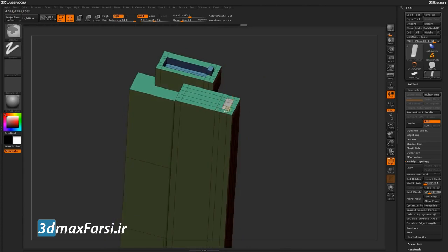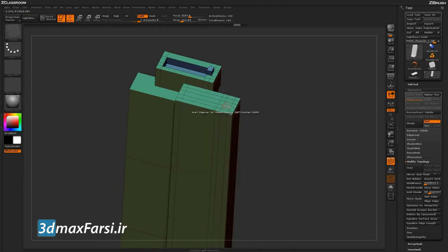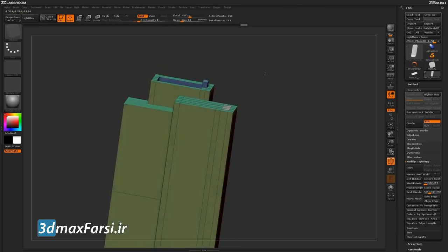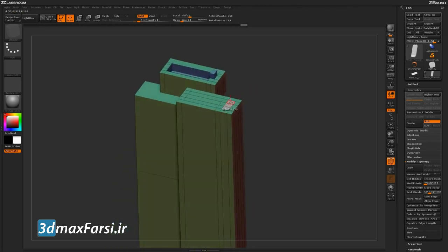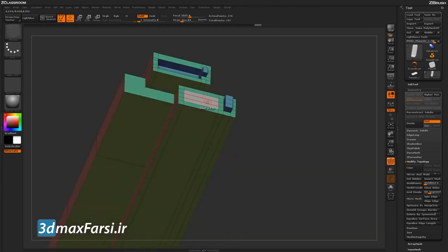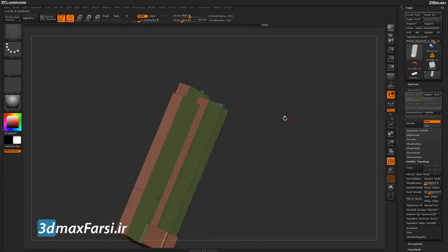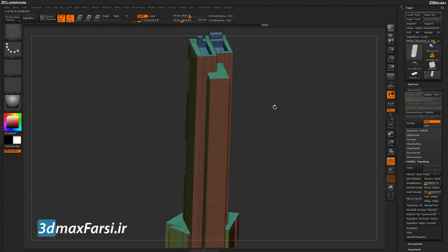different functionality. Now, if you want to apply the QMesh action across multiple faces, you could come in and hold spacebar and select a different target, or you can hold Alt and drag, and this will give you a temporary polygroup here, which will apply the action to that area. So this white polygroup, now wherever I click with QMesh a single poly, will apply the action across that entire area. So this will allow you to come through and target different zones on your model, and then apply the QMesh action like so.